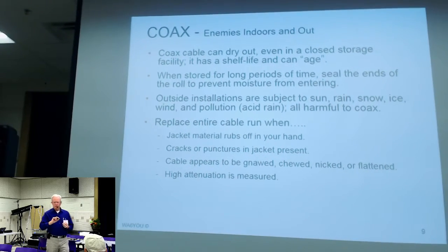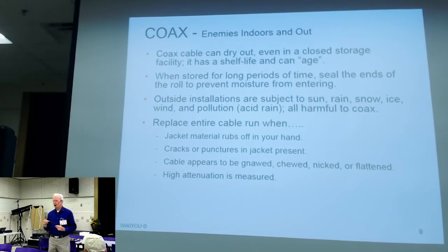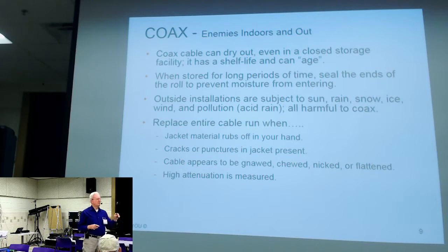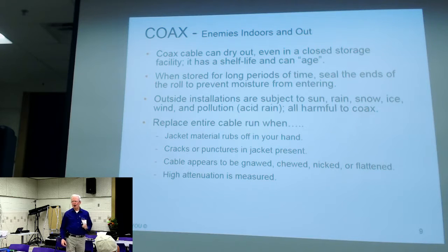And do most of you in here speak dB? Does everybody speak dB in here? Most of us? My dB loss of this beautiful 9913 cable is 0.3 dB. I have 94 feet of it. 0.3 dB at 7 megs.